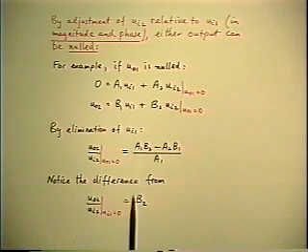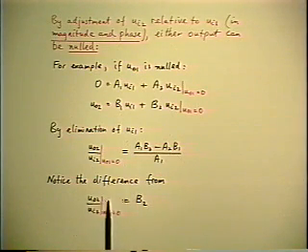Just to make it even more concrete, the meter that I'm using to do this is a narrow band voltmeter, which is actually part of a wave analyzer. And it has a 90 dB scale on it. So it's a very wide dynamic range, which is very good for demonstration purposes, because you can see everything happening in one range. And so we start out with readings that are on the order of 0 dB or minus 10 dB. And when I get a null, I can make it go down to minus 90. So it's a very sharp null because of the narrow band. So all of this is physically matchable in real hardware.